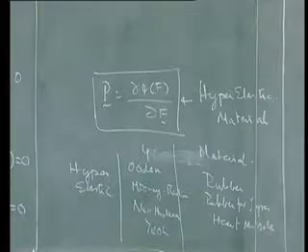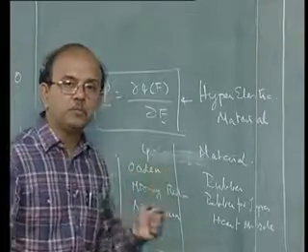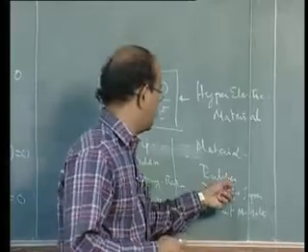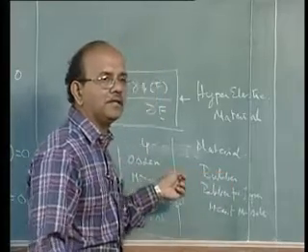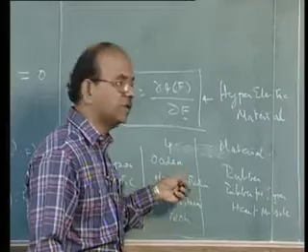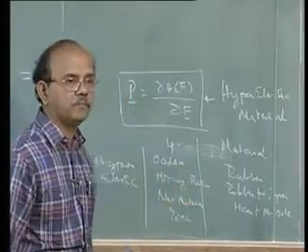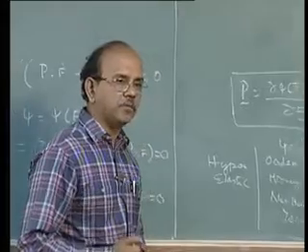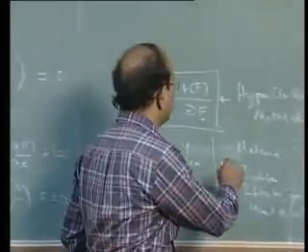As a next step, you now build a connection between the actual material and the mathematical representation of its behavior put forward by Ogden, Mooney-Rivlin, and so on. Now let us say that I can represent it using Ogden material, say a rubber, even a heart muscle.